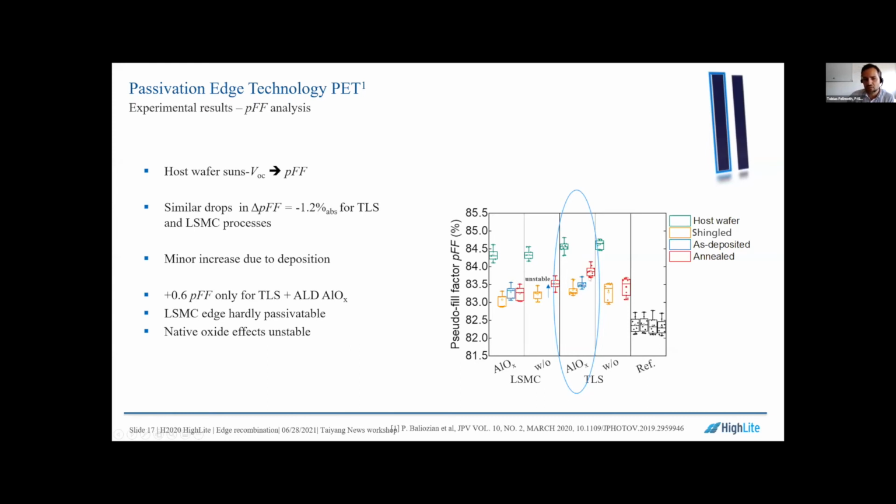So that means that you not only need to have a good passivation layer, you also need to look at your surface. By just using a standard conventional separating process and then trying to passivate it, it won't work. You need a smooth surface in order to passivate this.